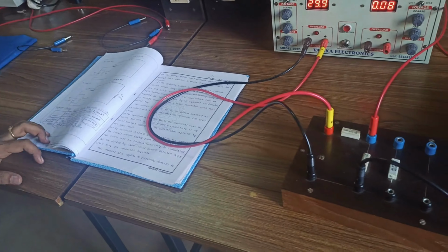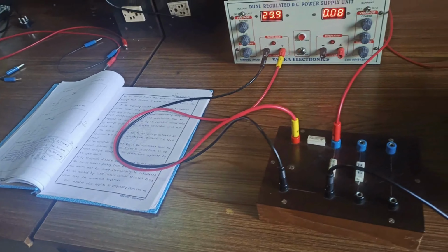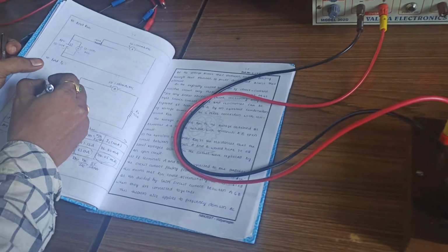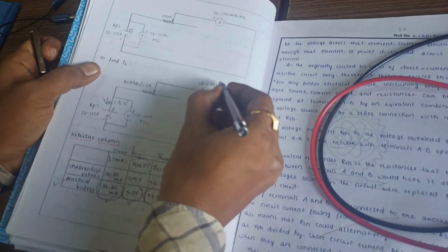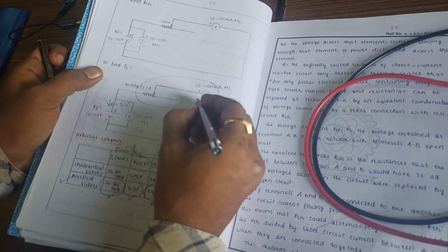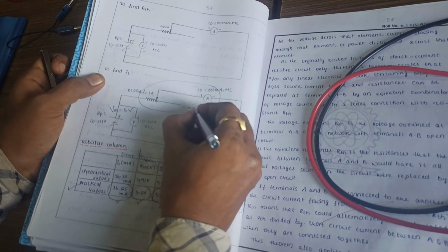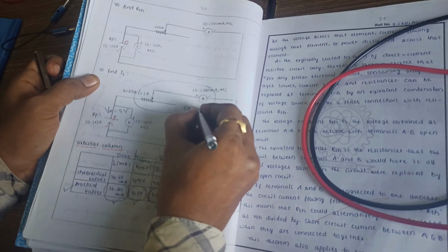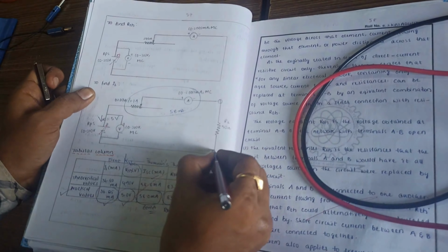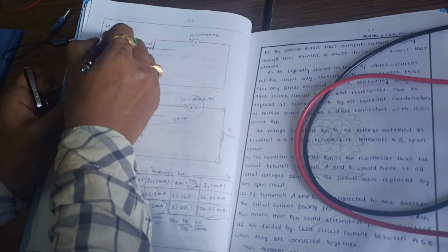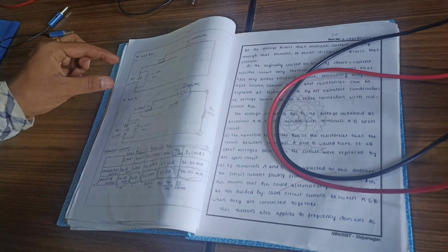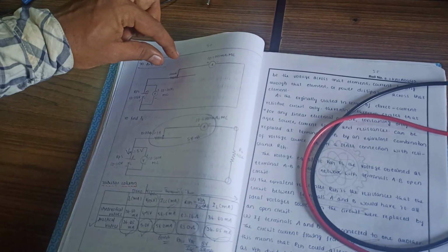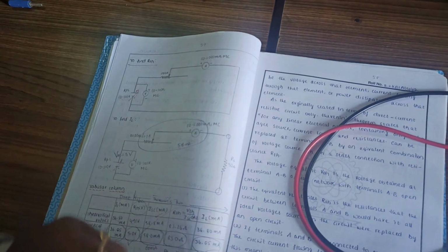Okay, the equivalent circuit you are going to have, so this is the equivalent circuit. Here we have to apply VOC as 5 volts, and through this network you have to get the short circuit current as 58 milliamps, and this is the load resistance. In order to construct this R Thevenin, we are going to construct this diagram. See this diagram: you have an RPS, you have a resistor, and you have an ammeter.